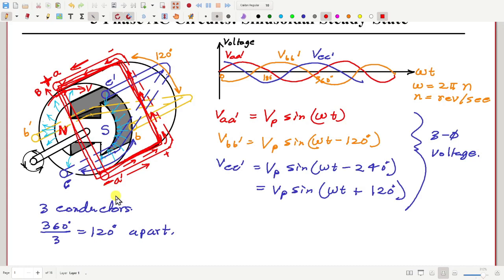So we will have higher amount of voltage. If we have only one turn, the induced voltage will be very small. Therefore we have many turns, say n number of turns, so that the voltage induced between the 2 ends of the coil, n turn coil, is significantly larger. So that is another fact.